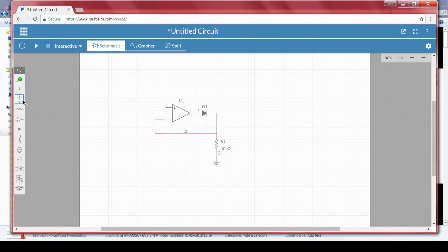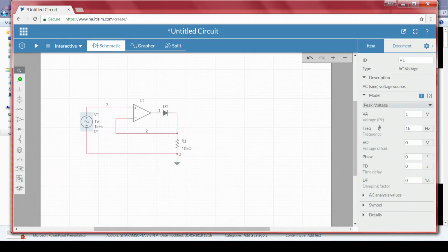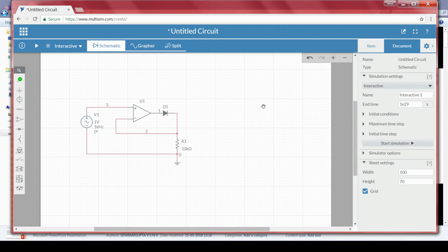Now, to understand the working of the diode, the working of our half wave rectifier, we will connect a sinusoidal input signal with a peak to peak value of 2 volts, because this signal is generally used to represent a peak voltage itself. Since we require the positive peak and negative peak as an input signal, it is easy to understand whether it is passing only the positive peaks or positive as well as negative peaks. So, we can take peak to peak as 2 volts.